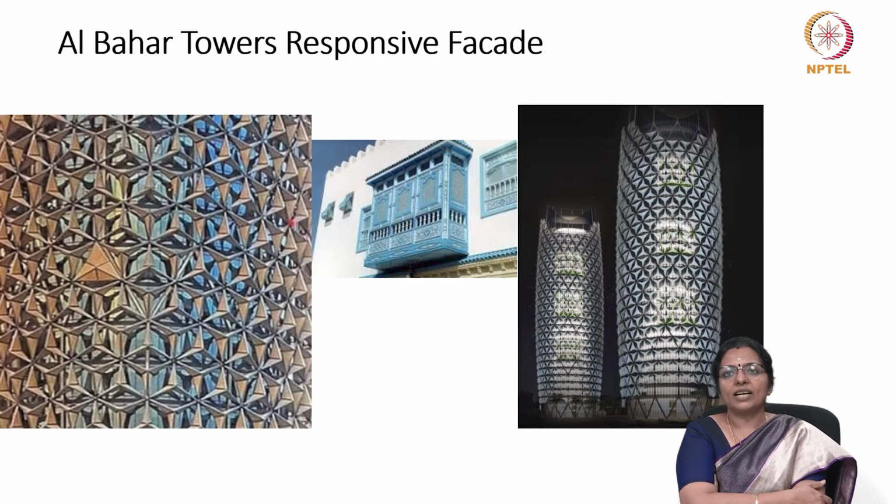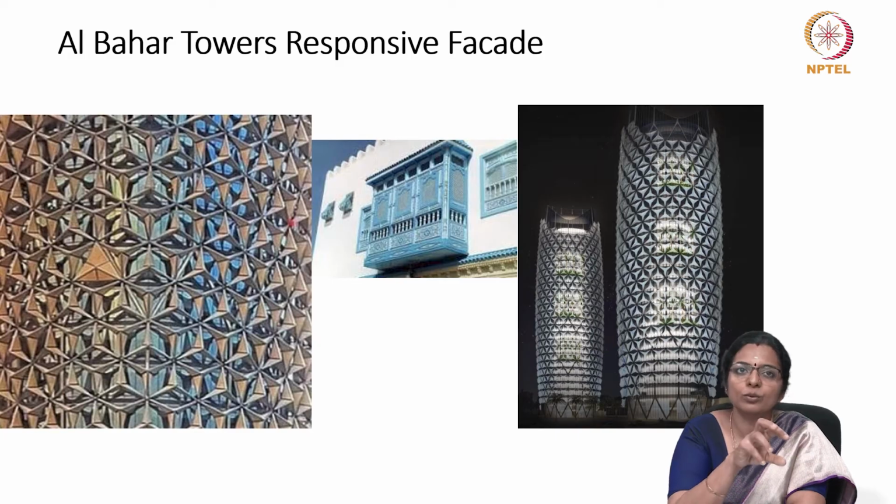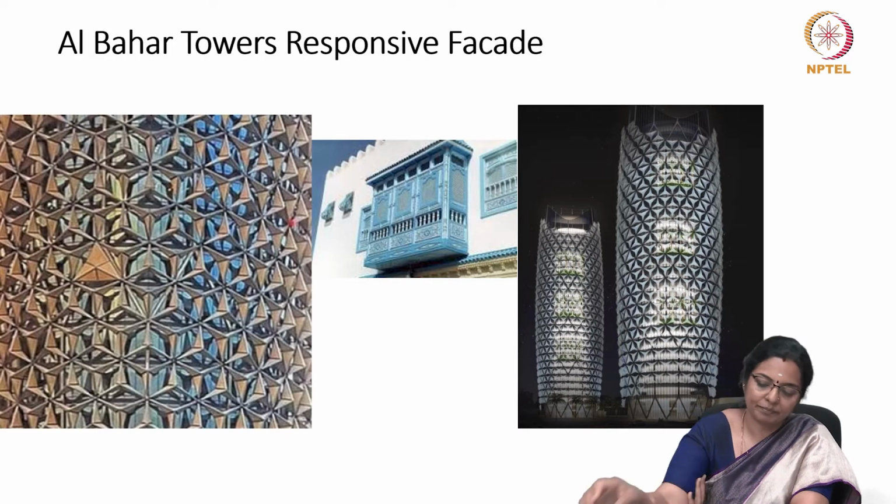Using a parametric description for the geometry of the actuated facade panels, this was simulated to operate as a response to solar exposure and the changing incident angles during different parts of the year as well as during different parts of the day.